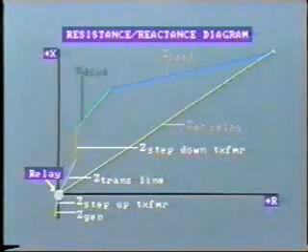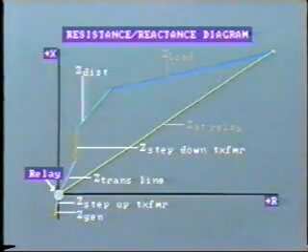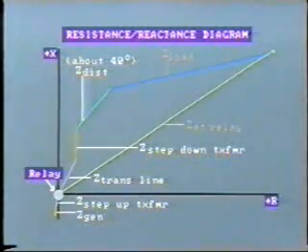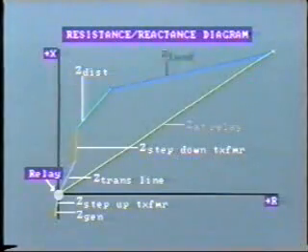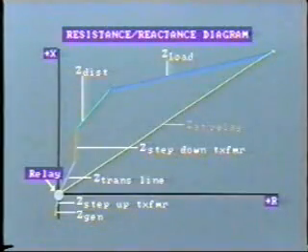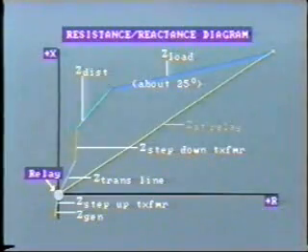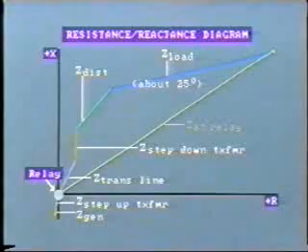And here is the combined impedance of the distribution line and distribution transformer. Note that the impedance of the distribution system is at a lower phase angle, at about 40 degrees. And here we add the impedance of the load, which is of much higher magnitude and also at a much lower phase angle. The power factor of the load is generally in the order of 0.9 to 0.95. The corresponding angle to a cosine of 0.9 is about 25 degrees.